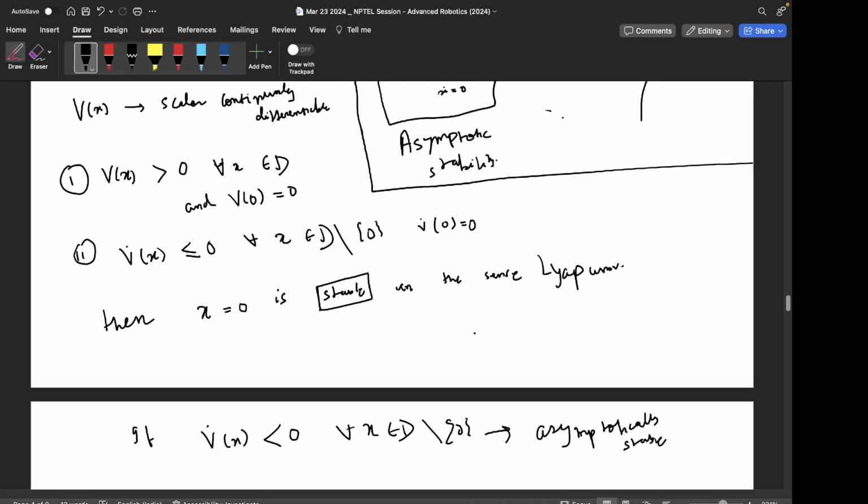I mean, it depends. There will be a few more things. The associated thing is the region around the point which you are considering. If the region is small enough, and you are talking about practical scenarios, and you can work with your state being in that region, then it's fine. But you're right that in most cases we go for designing asymptotically stable systems, where the error goes to zero.